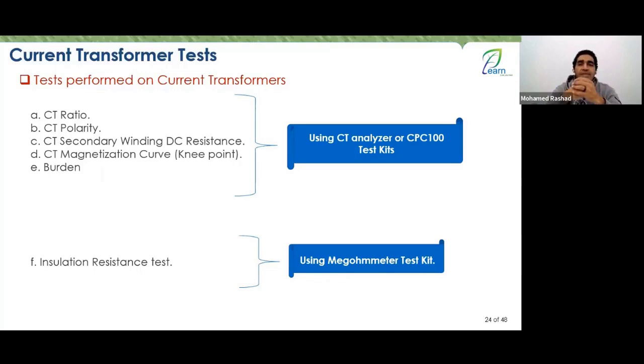So what is the necessity of subtractive and additive? We said, well, mine is additive. As a current transformer, it doesn't make a difference to me, but it matters when I connect this current transformer to the metering device or the protection device, because here the directionality or the correct reading of the current direction is very important to me. If I connect the current transformer secondary circuit to a meter device, whether analog or digital.